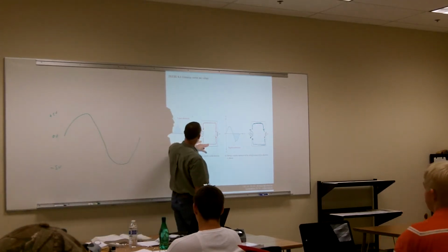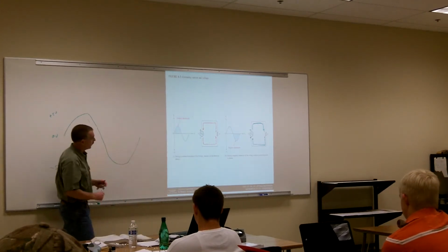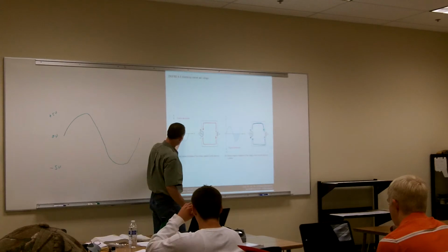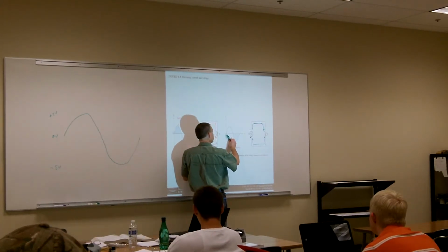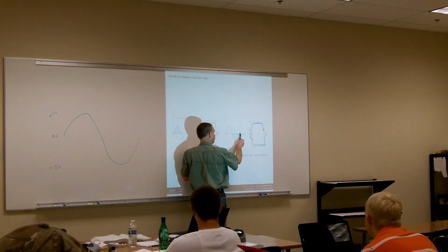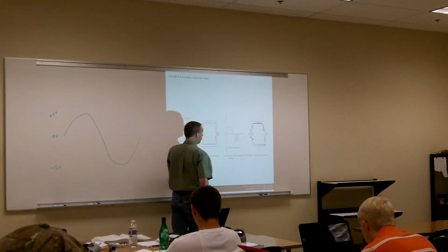Well, if I do that really fast, my multimeter won't be able to see that. So we'd have to use an oscilloscope to get that graphical representation. If I'm measuring my voltage across my resistor, it would look identical since I only have one component in there. That component is going to drop all the source voltage. And on my oscilloscope, I would see this same kind of waveform.